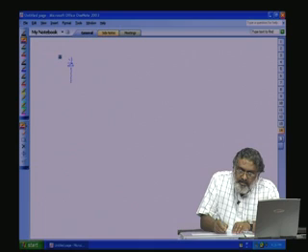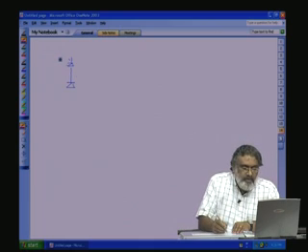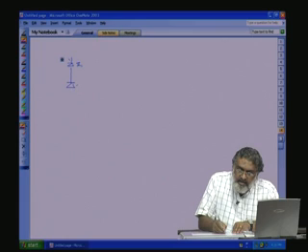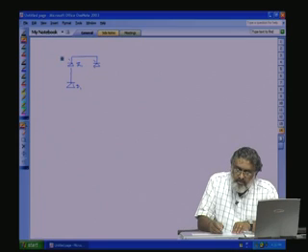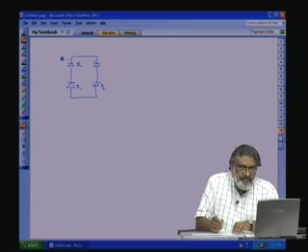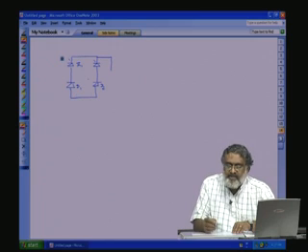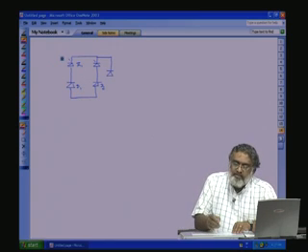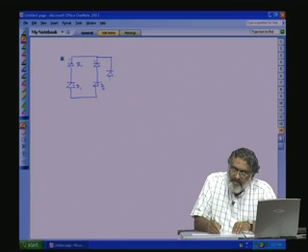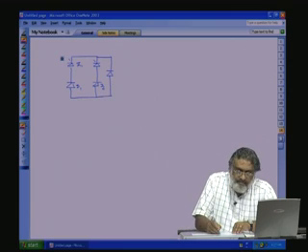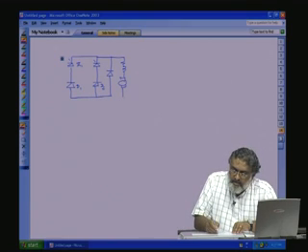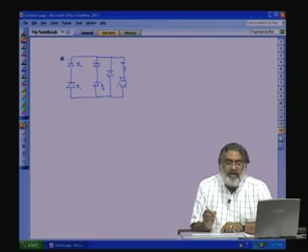Okay, this is the diode D1, this is TH1, then TH2 and D2. Now, instead of having the freewheeling through the thyristors and diode, we will give a small low impedance path that will connect the freewheeling diode across here. Then we have the load. So, here is how the conduction happens.